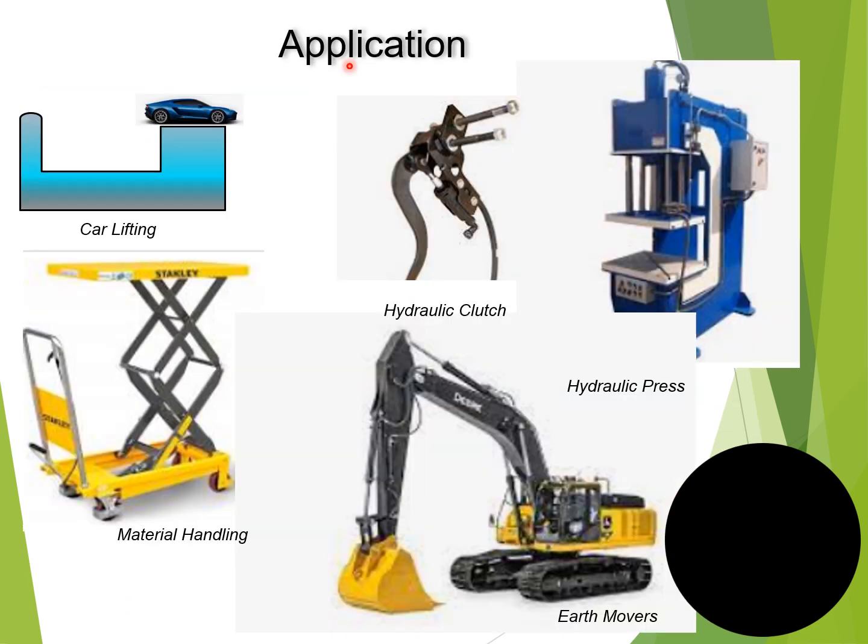So these are the applications of the hydraulic circuits. First is car lifting. This is a car. We have referred to this diagram more than once. First in Pascal's law. This is a narrow area. This is the larger area. Pressure is the same. If force is applied here, then it will get converted into a higher force in proportion to the area. Then the hydraulic clutches in the automobile.